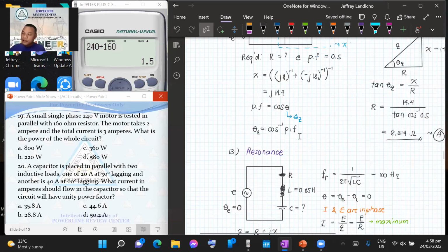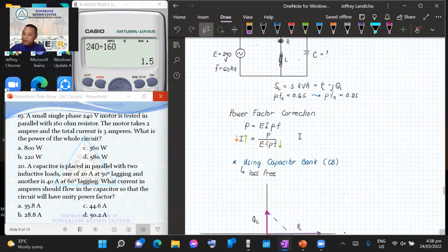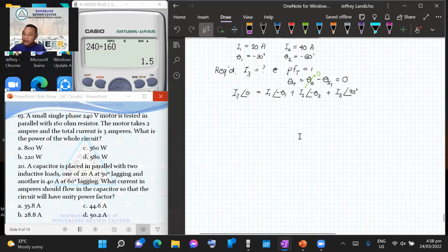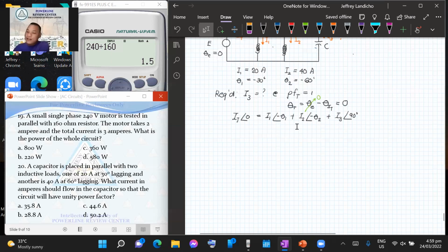So using only parallel operation, you can get our I sub 3. You can now compute that. You get 44.6 ampere. So you try to compute. Okay, those are our final answers. So we haven't changed anything: in parallel, current is additive. You just have to include the corresponding angle and use complex numbers. That is why it is important in AC circuits to be comfortable with complex numbers.